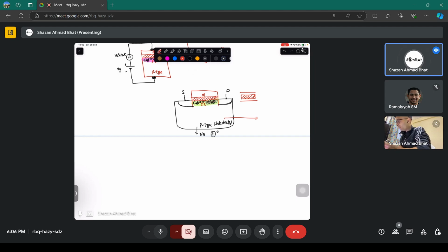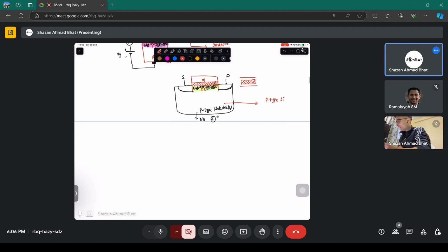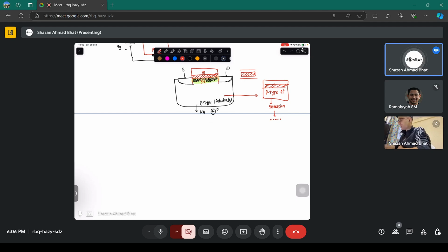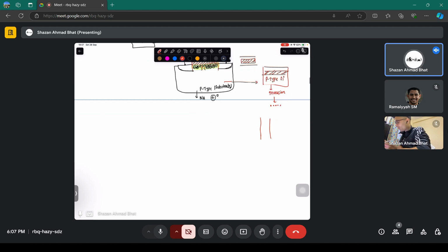If you have a p-type semiconductor, a p-type silicon or a p-type substrate, in case of a MOS, then upon inversion, when you invert the channel, you know that electrons are going to be present at the oxide semiconductor interface. You remember applying a positive voltage on the gate side, VG, and a negative voltage on the semiconductor side.